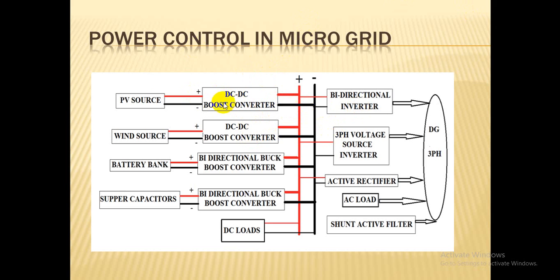Okay, and also you are able to take the feedback. For example, here you are taking the feedback of solar PV panel voltage and current, and then here wind voltage and current, and then here battery voltage and current, and then you have to find the SOC by the Coulomb counting method or whatever method, and then you have to do the current control, hysteresis control. So the control technique also you can develop in the FPGA, okay, in parallel. So why? Because if you are using a separate controller, there must be a fluctuation of power flow, some small ups and downs in the common DC link.